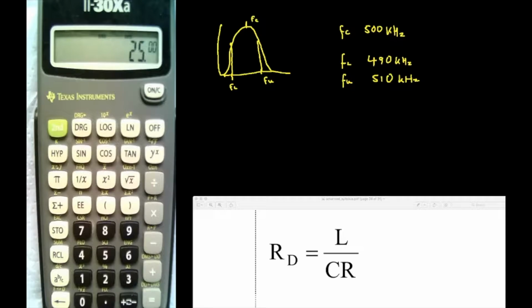I would enter the figures in using engineering notation, because C will be something like microfarads or picofarads. L may well be in millihenries. I would enter in the bottom, divide it by the top, and then flip it using the 1/x key afterwards as being the simple way of doing it. Having said that, I will go through this one and we'll use it as an introduction on how to use brackets.